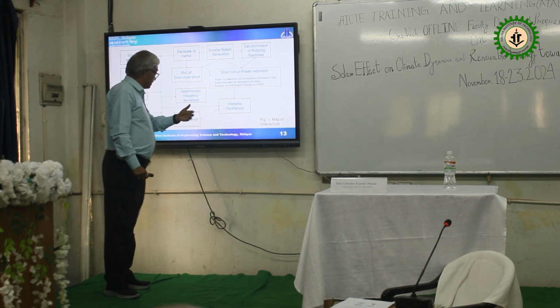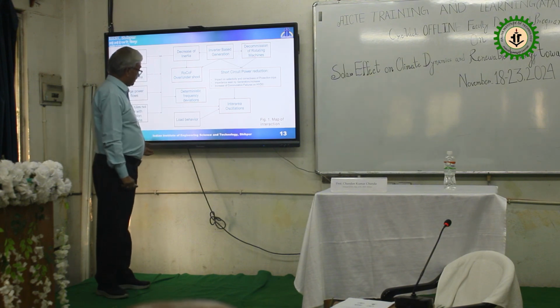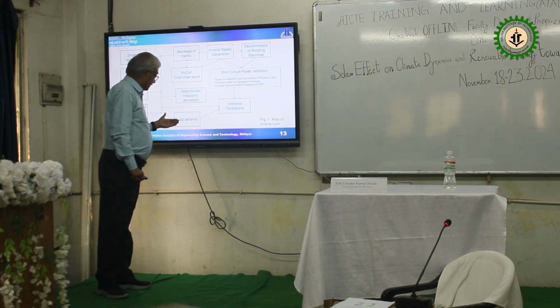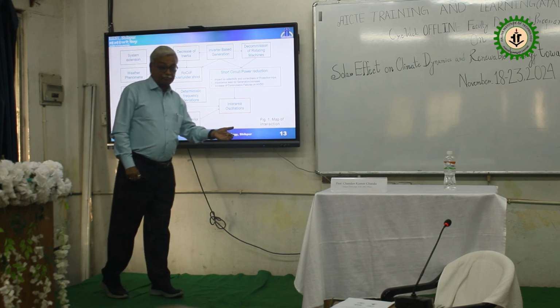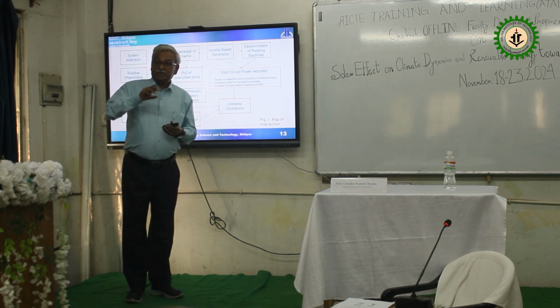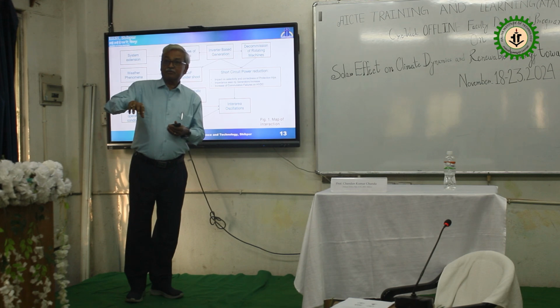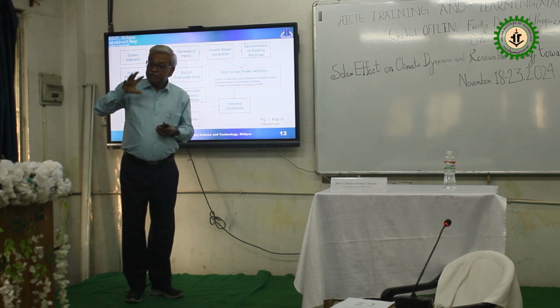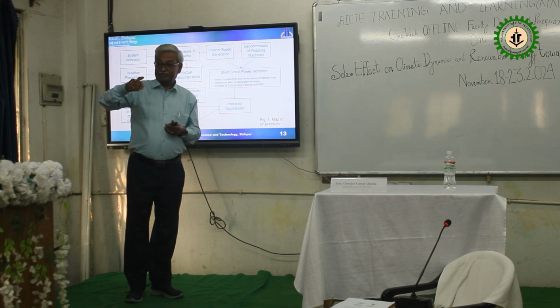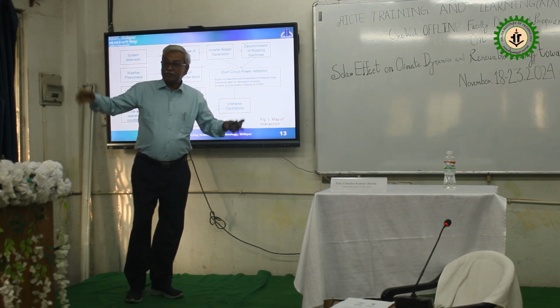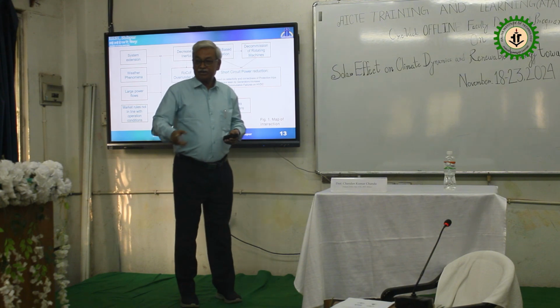So deterministic frequency deviation is there in the system, and inertia oscillations come. I told you in the morning how we get inertia from the synchronous generator. Another inertia we get from the load side, because in the load there are a lot of rotating devices, induction motors, synchronous motors.